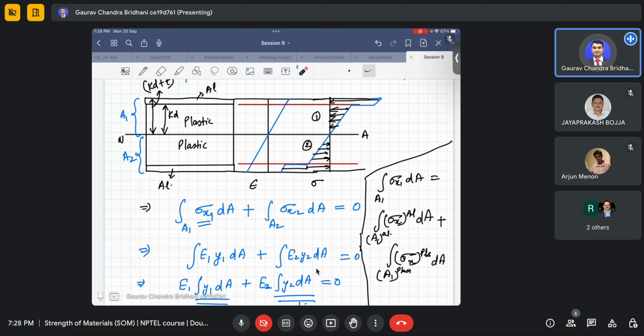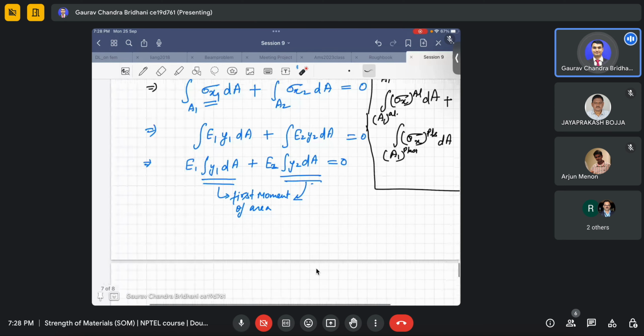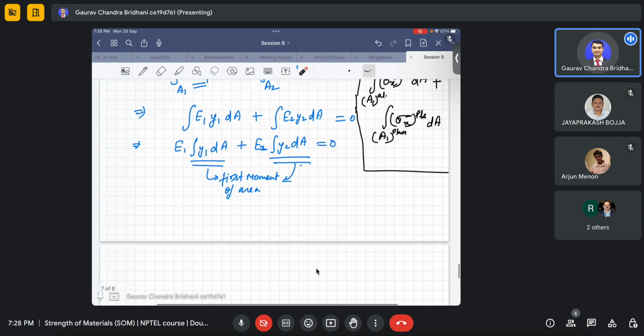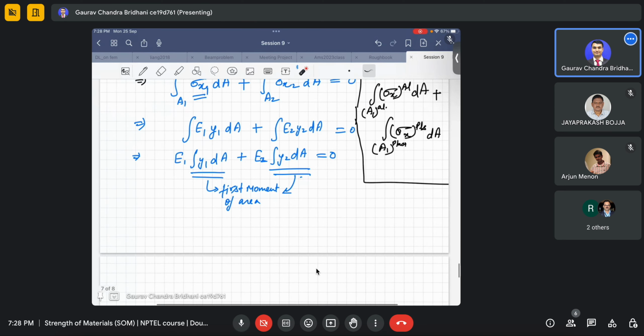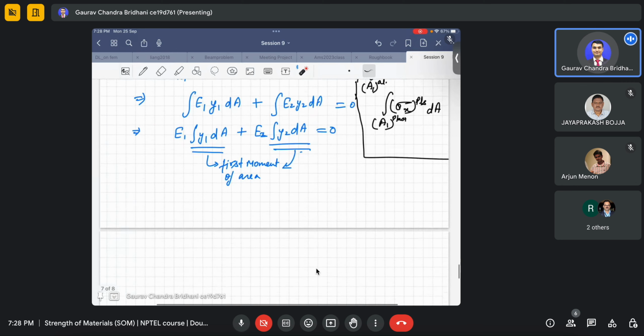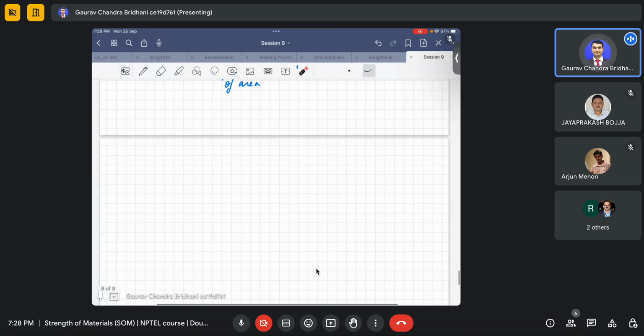It will come actually as a quadratic equation, so you will have two solutions of it. One will be negative most probably, and one will be positive, between 0 and 1, and the positive one is the answer. In this case you will find it is just half, 0.5, because it's a bisymmetric beam. By adding the plates, symmetry is achieved.